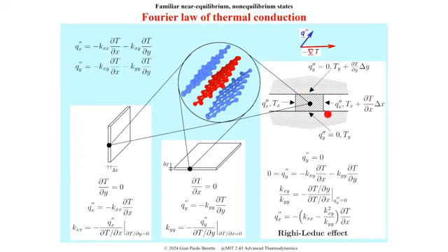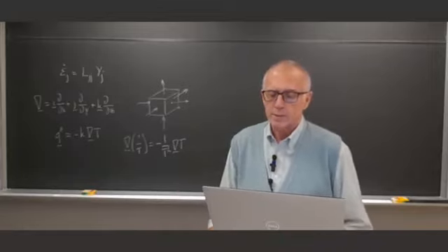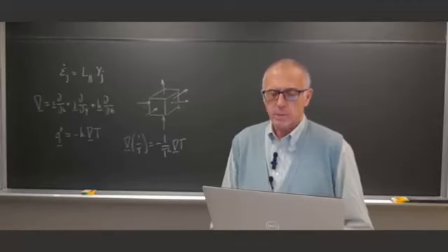Notice also that, for example, using this idea, you can construct a non-disturbing heat flux sensor, because in here, by putting the thermocouples across the sample, which are off the way where the heat flux goes, by measuring this temperature difference, you measure the heat flux, and therefore you don't have to put thermocouples in the way of a small sample, because typically if you put the thermocouple, that will disturb the measurement because the thermocouple has its own size, and therefore it alters the actual situation. Okay.